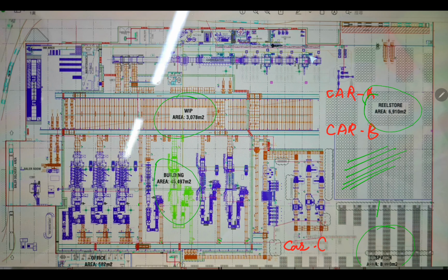It makes problems, with different types of errors coming in the PLC or programming or another production management system. So it's better to separate and make a partition between the communication cables, control cables and the power cable.